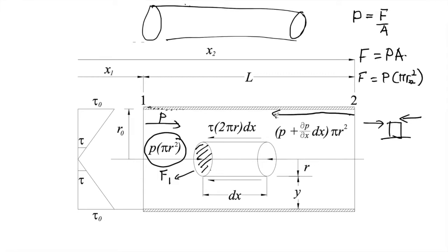So how do we calculate the force here? We know that this is P, and this is delta X, the change of X. To know the pressure here, it is the change of pressure over the change of X, since pressure changes based on X. So to find the force here, we write P plus dP/dx times dx, and times the area.